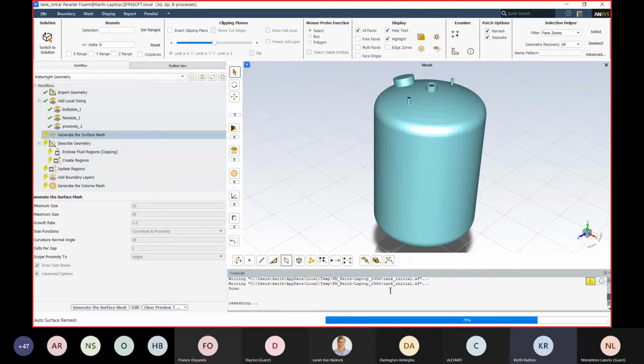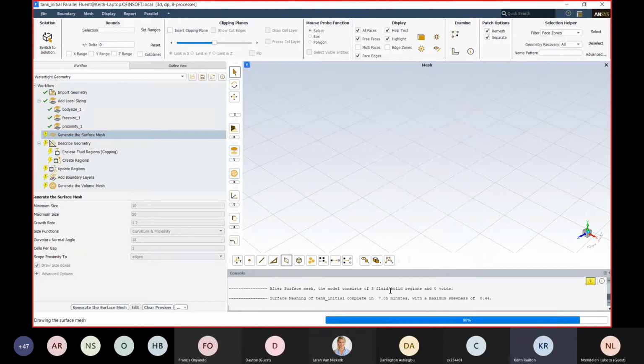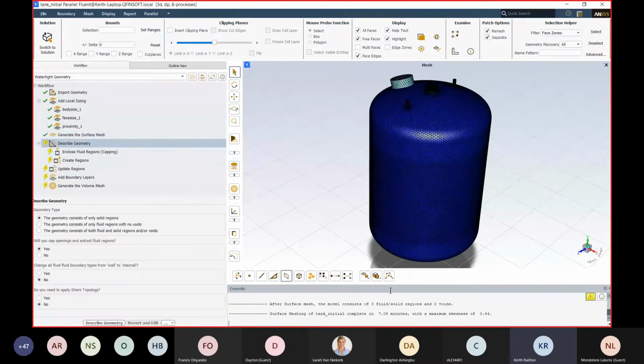Okay, so there are a number of ways that we can do mesh adaption. The first would be just a manual import, where you could work through Workbench, where you can drive these different dimensions. Alternatively, you can just do it by yourself. I would copy this mesh, change my refinements on these body sizings and my surface mesh, and then from that I can refine and refine. So that's one way of doing an actual mesh refinement study.